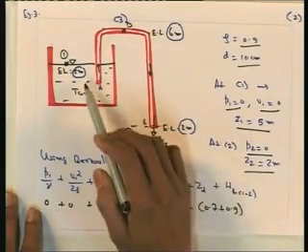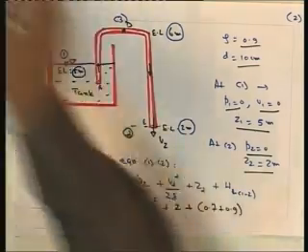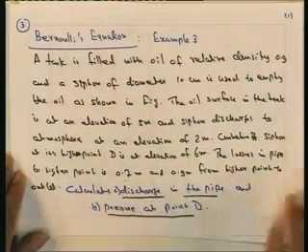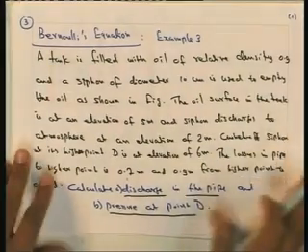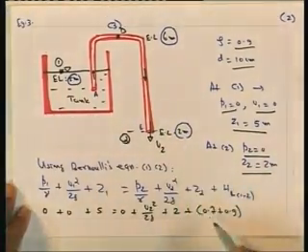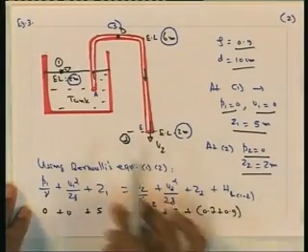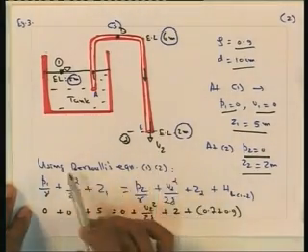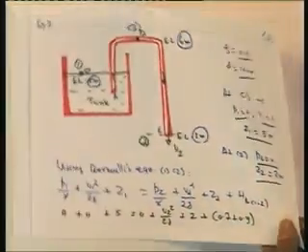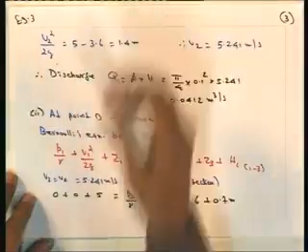The head loss is already given in the problem. The losses in the pipe to the higher point are 0.7 and 0.9 from the higher point to the outlet. So, these are the head loss from section 1 to 2. So 0.7 plus 0.9, this is also added, and then we use the Bernoulli's equation between section 1 and section 2. Now we can write V2 square by 2g is equal to, we get an expression for the velocity.